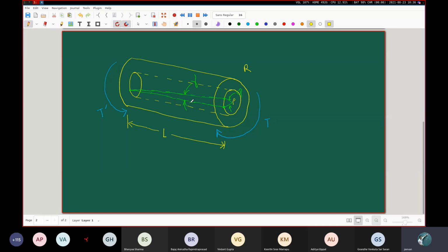Now you tell me, using gamma, phi, rho and L, can you give me a relation between gamma and phi? So L gamma equals rho phi. Gamma into L is equal to rho into phi. For people who have understood this immediately, well done. For people who may be taking a minute, the clue is that you are basically equating this arc. Considering this circle, this arc has the length rho into phi, and considering this particular geometry, that is approximately equal to gamma into L.